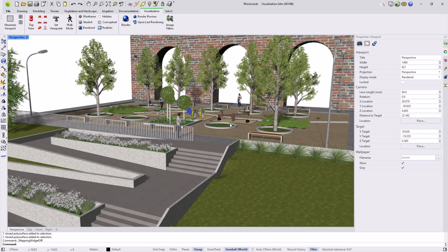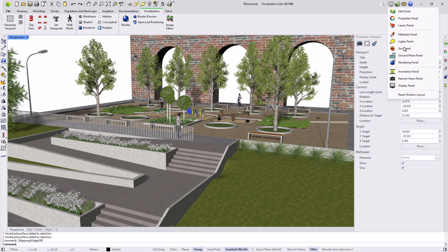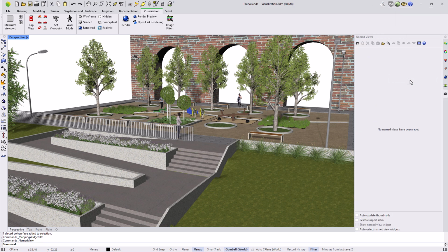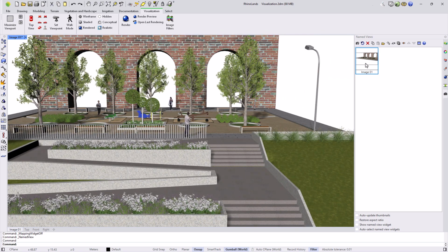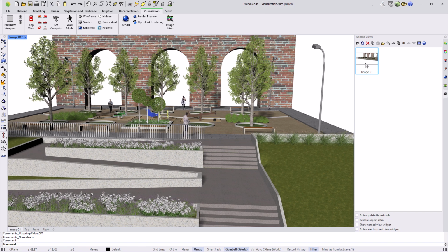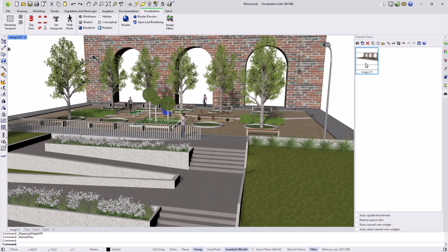When we have the desired view, we save it from the Saved Views panel. To do this, we click the camera icon with the plus symbol, assign a name to the view, and upon accepting, the view is saved along with a thumbnail in this panel. This is essential when we need to use the same viewing angle with different settings, whether for lighting or even to compare seasonal changes in vegetation. This way, whenever we move the view, we can return to the saved configuration by double-clicking on the corresponding thumbnail. We can save a multitude of views that we are going to render in this panel.